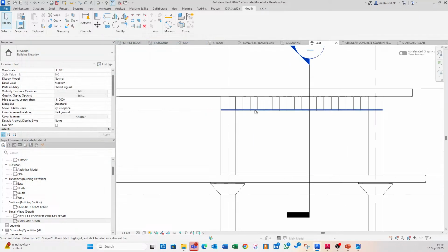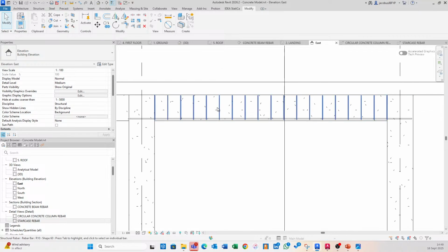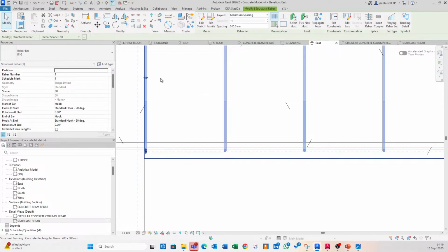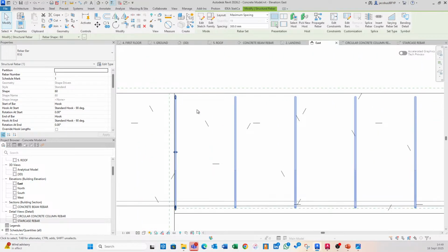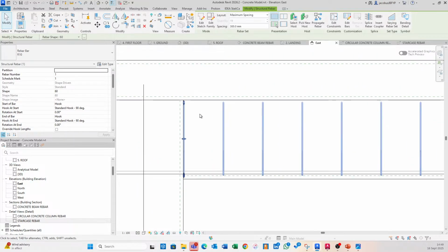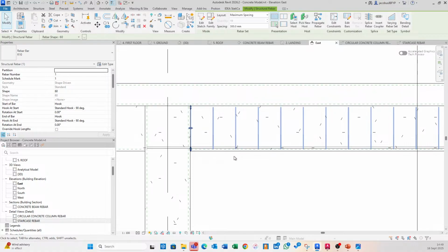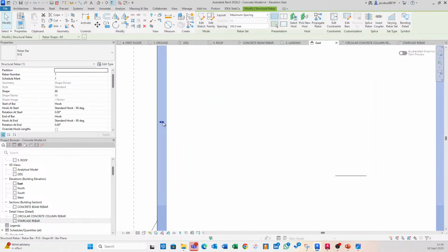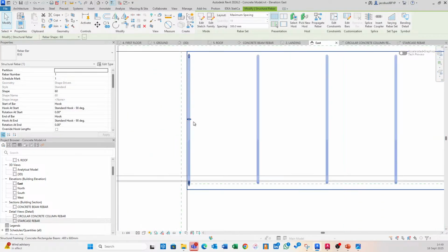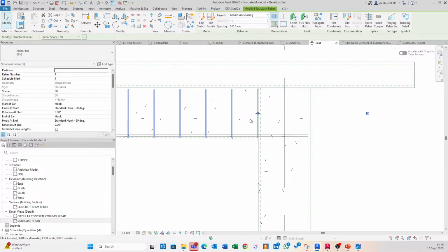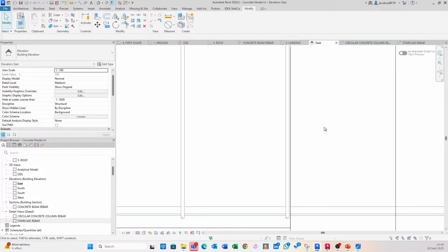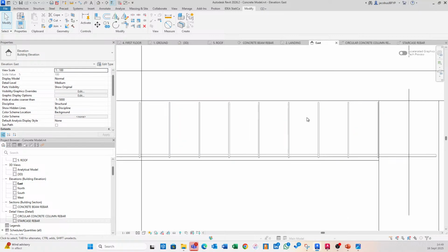Okay, so first and foremost, when we do our detailing, we usually have only one bar displayed in this kind of view. And you'll notice here as well that these bars go all the way up to the face of the column. Now, that might be realistic because these would be cast monolithically. But if you want to move them slightly back, that grip is really, really helpful. So I just clicked it twice just to move it slightly back from that column face. I'll go over here as well and just click it twice. Okay, and that's going to be useful when we start doing our detailing.